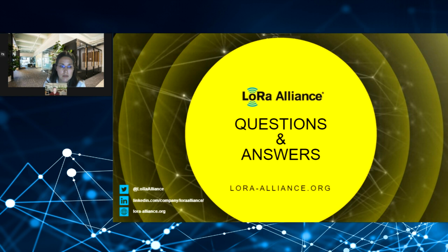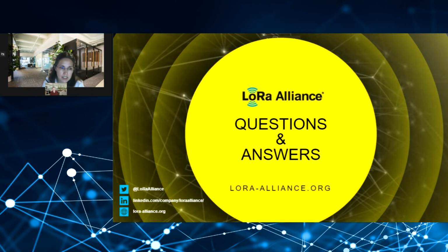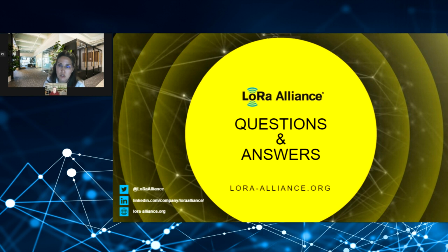Okay. Very good. Here's one. How do I ensure my setup is correctly configured and my gateway is running properly? Indeed, this is a good, interesting question. I would always recommend using the LCTT to configure the gateways, in case the gateway is capable of this and the LCTT is compatible with this gateway model. In this case, you will ensure that the gateway is configured with the right settings, with the IP address of the computer, with the correct channel list, and everything.